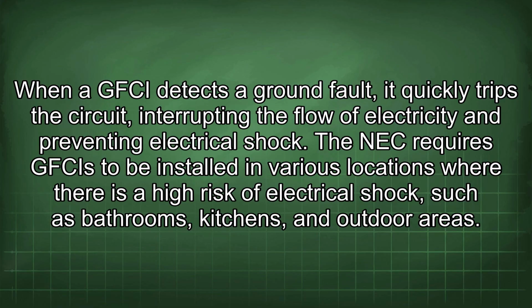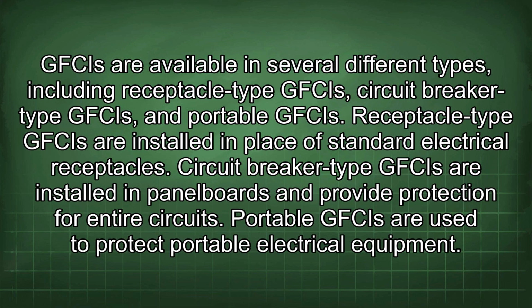The NEC requires GFCIs to be installed in various locations where there is a high risk of electrical shock, such as bathrooms, kitchens, and outdoor areas. GFCIs are available in several different types, including receptacle-type GFCIs, circuit breaker-type GFCIs, and portable GFCIs.